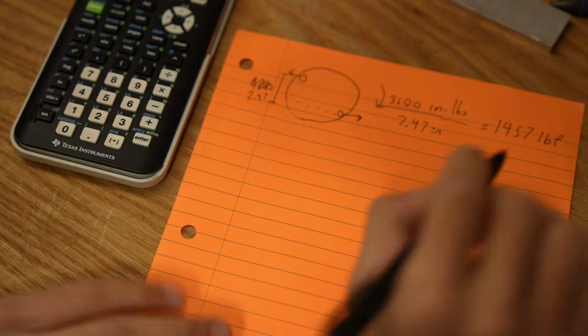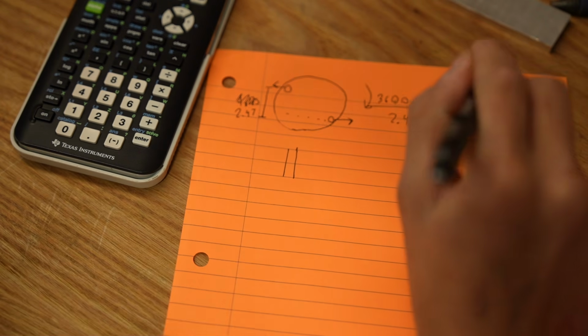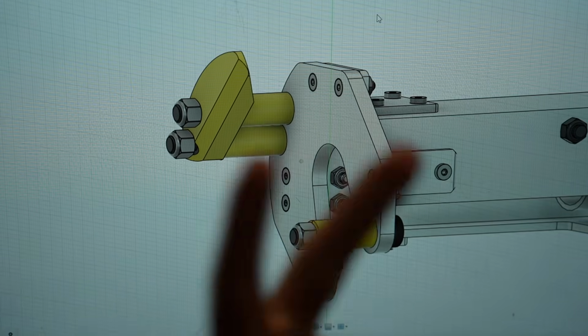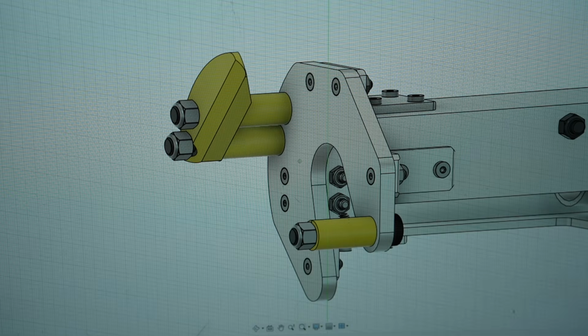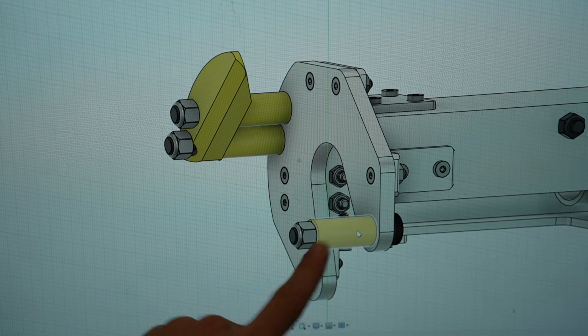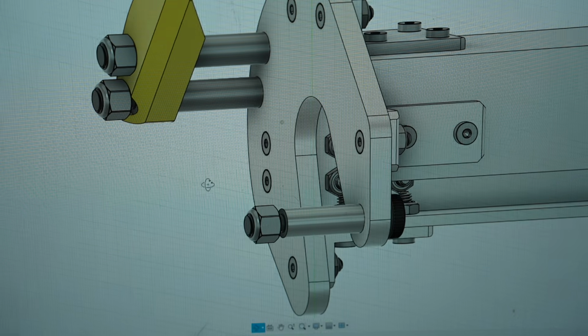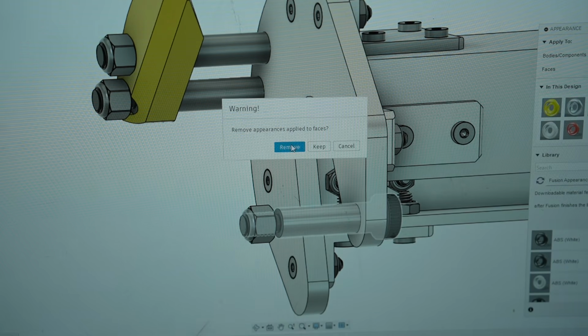So first we're going to analyze the nubbin. We're going to a side view. If we look back to the CAD, we're actually going to do our math with two assumptions. Always know the assumptions you're working with. If you disagree, you should do your math with different assumptions. We are removing our outer sleeve here because that is non-determinate and kind of shares the load with our bolt, which is a conservative assumption because the outer sleeve makes the bolt much stronger.